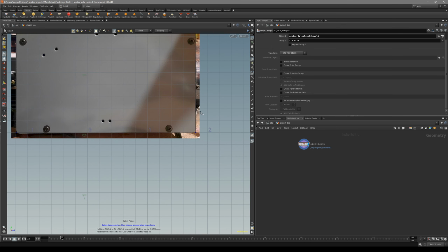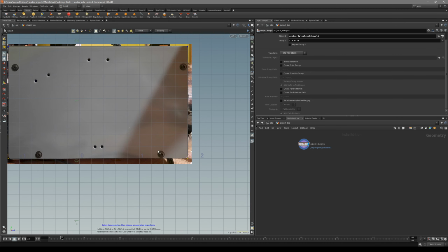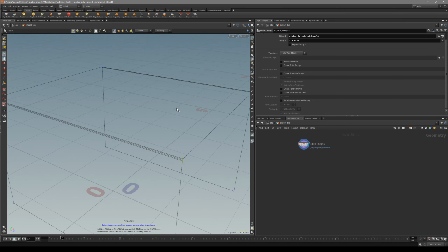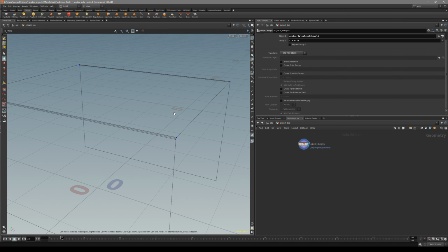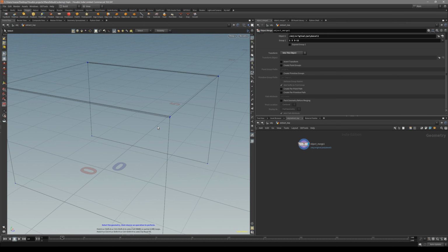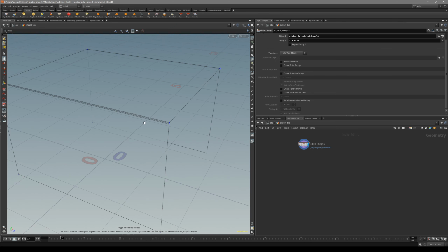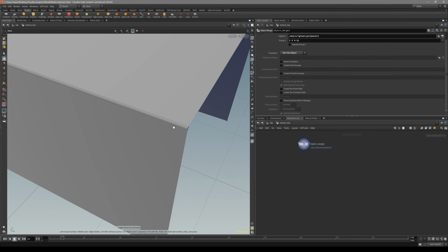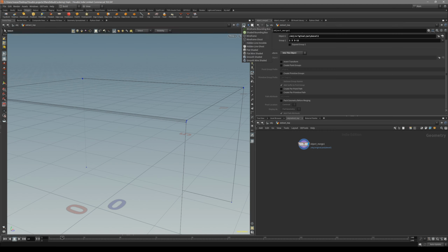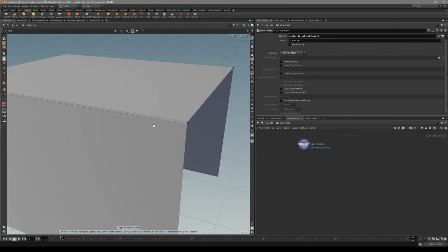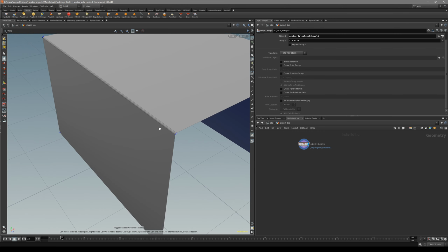So now you can see we have true wireframe. We can select vertices and bevel them and whatever we want. So there are the two selections, but you can see that now my hotkey Alt R is basically switching between wireframe and wireframe ghost. For me to get back this functionality, we have to go back to smoothed view, and now it's going to toggle between smoothed view and the wireframe ghosted mode. So that's how that works.